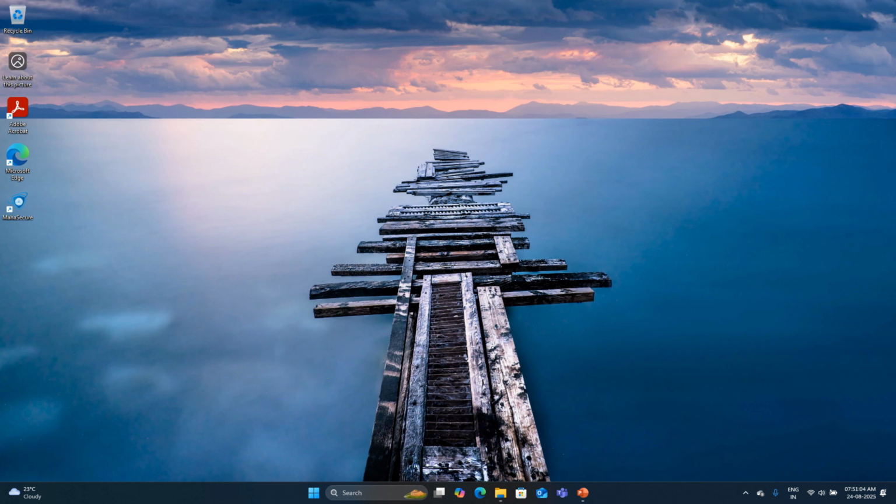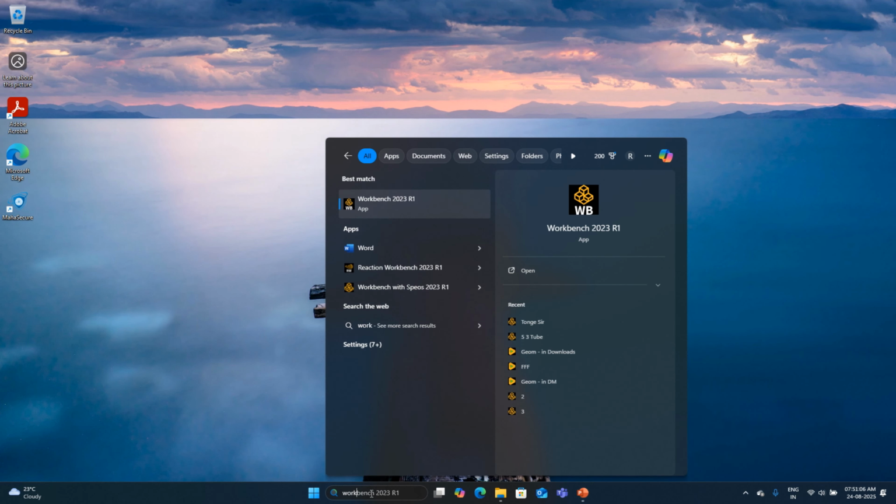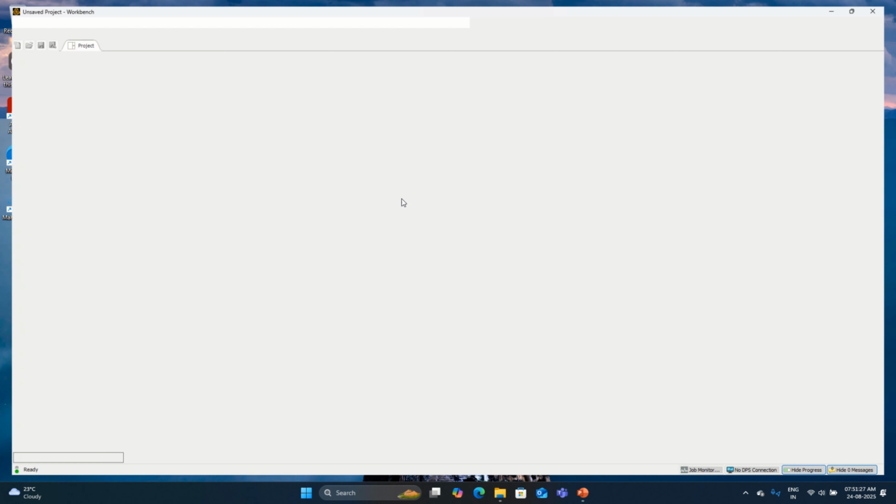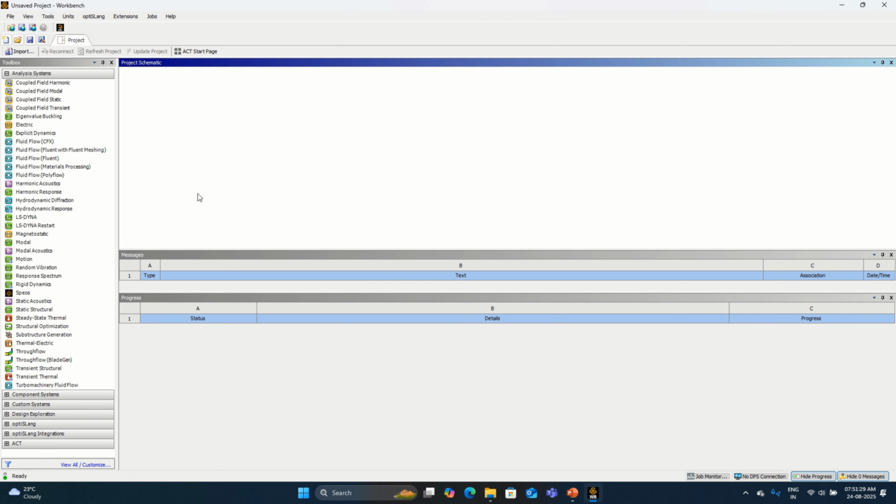Today we will see the CFD simulation for a fluid flowing over a horizontal cylinder. For this we will prepare the 2D geometry, and we will see how this analysis can be done with the help of a 2D geometry. We need to prepare sketches, create a surface from the sketch, and then proceed to meshing and the other parts. So let's start with the Fluid Flow Fluent option.